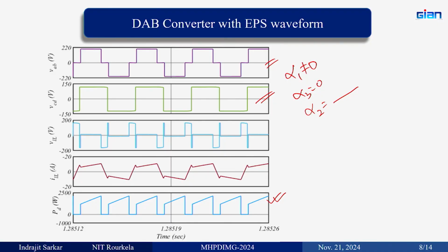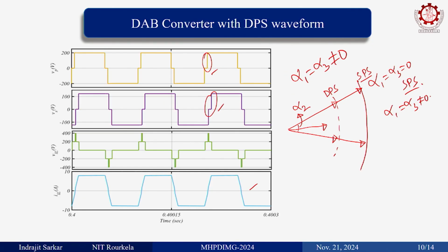That solar inverter feeds power to the grid, and when connected to the grid it is in current control mode. In islanded mode, you have to give a voltage reference and frequency reference in order to work in standalone mode.